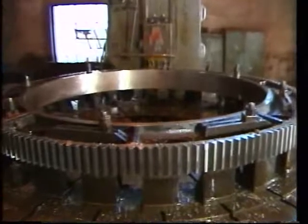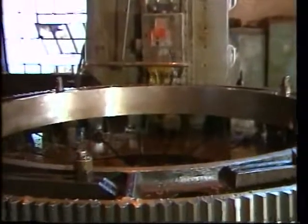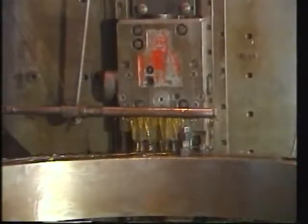In case of large gears, an initial rough cut is made before taking them for gear generation in order to quicken the process. Gear shaping using rack cutter is one of the gear generation methods.